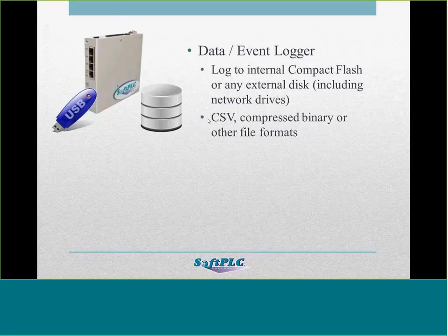Soft PLC can also be a data logger. Maybe you don't need to do any control, you just want to do some data acquisition and logging. We can do that. And there are a number of blocks that we have to do data logging to different formats. So we can go to CSV, you could go to a database format, or we have a binary format for high volume logging where the file is going to get very, very large, and or you're doing very high speed logging and you don't want to be doing it to a text format.